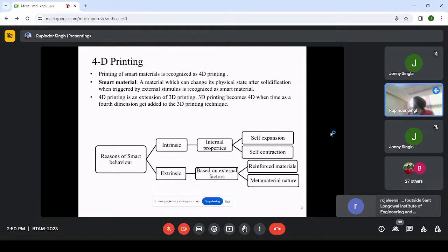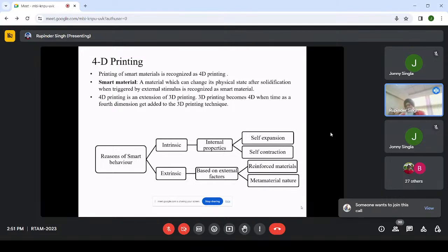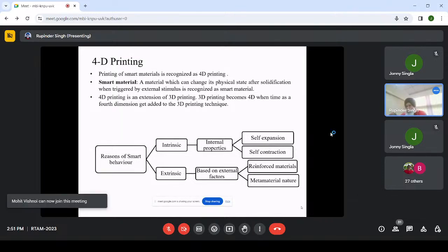When I apply a load over a quartz crystal, it changes its dimension. Now you release the load, it will come back to the original position. If I do this exercise, applying a load, releasing a load, n number of times, I get the same displacement. And this change in dimension or change in length is calibrated for the force measurement, which is digitally displayed on my instrument, right?